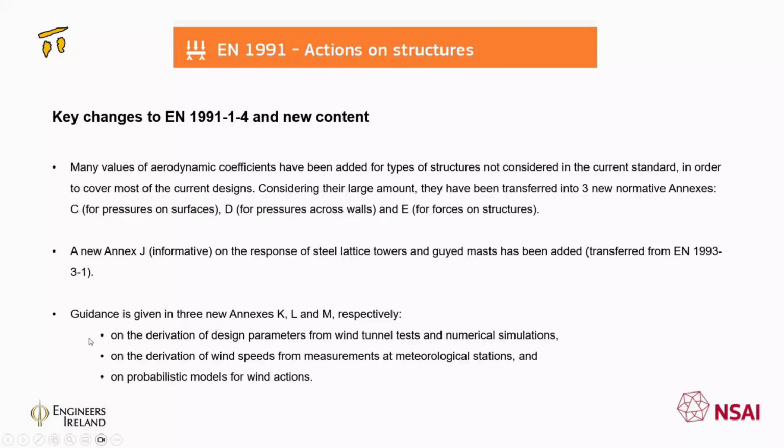There will also be, as for snow and the thermal actions, new Irish loading maps brought into the next generation Eurocode based on studies carried out recently by Met Éireann in relation to the Eurocodes. So the further changes here: they've brought in many values of aerodynamic coefficients for types of structures not in the current standard.